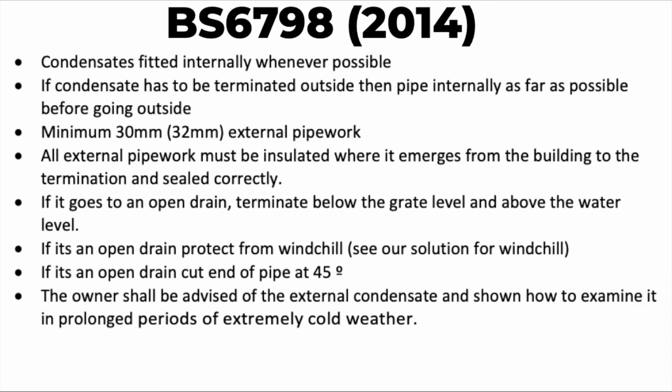If it goes to an open drain, terminate below the grate level and above the water level. If it is an open drain, protect from wind chill. See our solutions for wind chill. If it is an open drain, cut the end at 45 degrees. The owner shall be advised of the external condensate and shown how to examine it when there are extremes of cold weather.